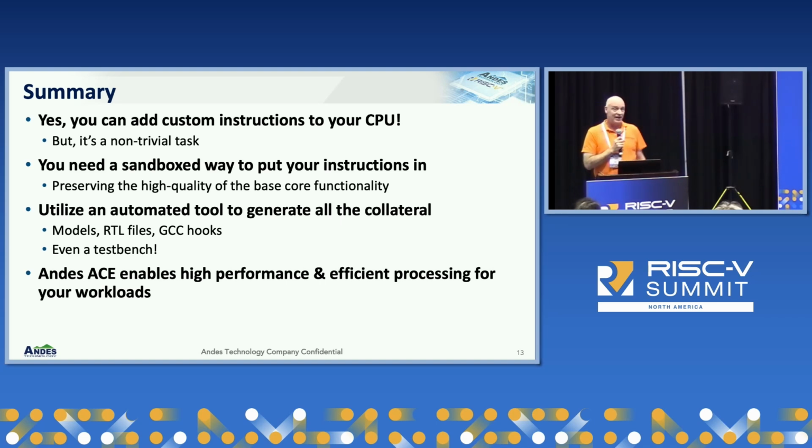And of course, we have the automated tool, which gives you all of the collateral that comes with it: your golden models, the full RTL, your decoder, your opcode assignment, and you even get a test bench. So I think this is the right way to do it and the safe way to add instructions to your SoC and to your processor.